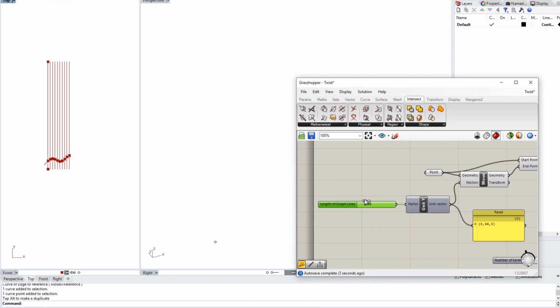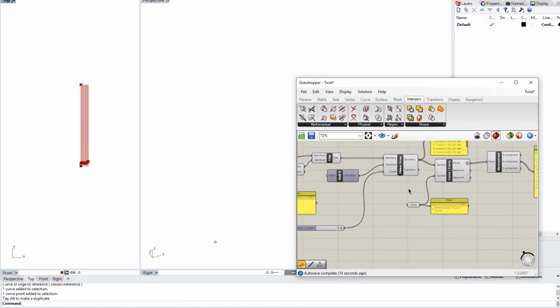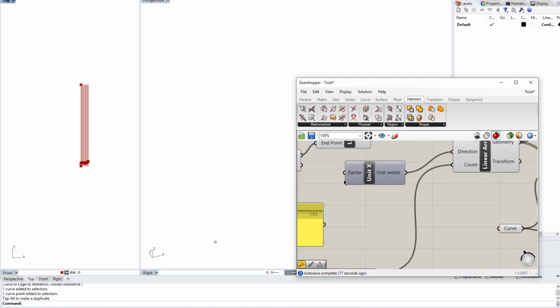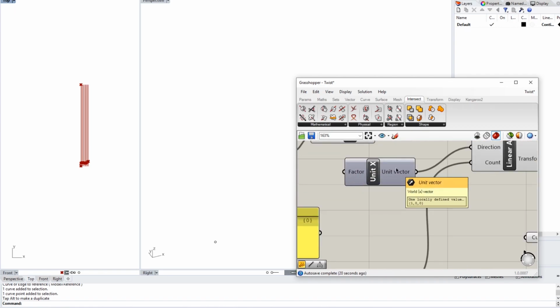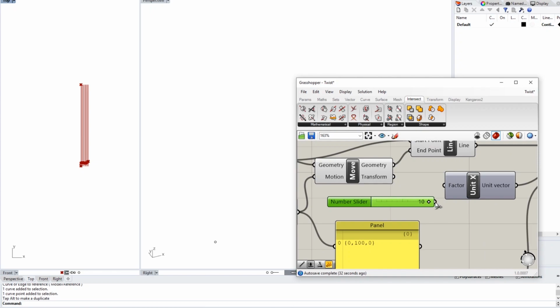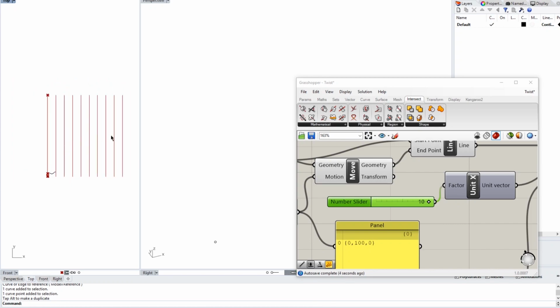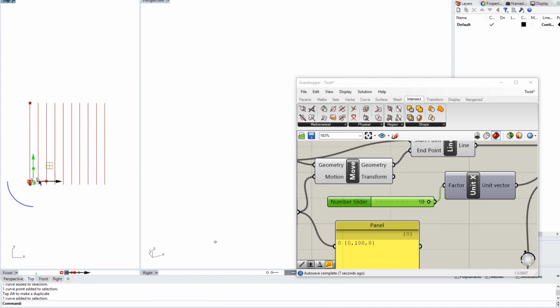So what I'll do is extend it much bigger. Let me see. Okay, so double click to change the value manually. 100. Okay, let me zoom it out. We would like to change the intervals as well. It's currently governed by this factor, and instead of moving the lines only by 1 unit, we would like to move it by 10, maybe 100. Let's double click. 10. Enter. So now we would like to move the lines by 10. So basically you're scaling the graph. And you would like to scale this one as well.